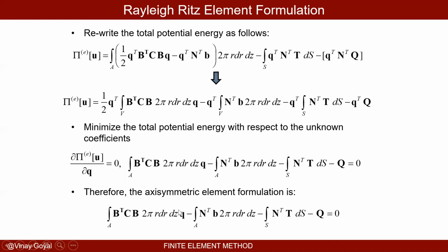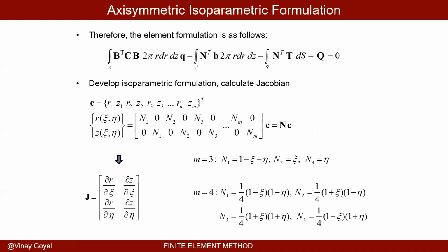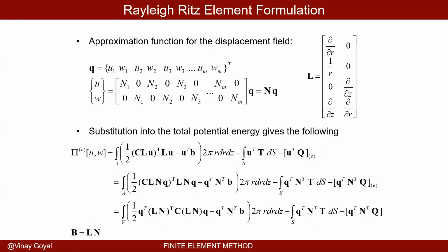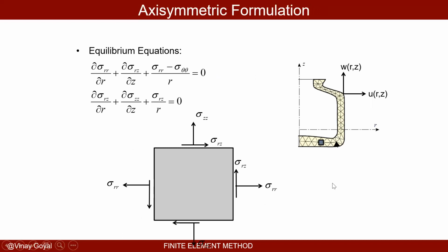And I want to solve for Q bold. That's my goal. Body forces could be provided, traction forces could be provided, the shape functions are known. So all these integrals are known. B bold is known, C bold is known, B bold is known. I can integrate that. The only thing that's not known is Q bold. And like I said before, every triangle element here is going to have different shape.